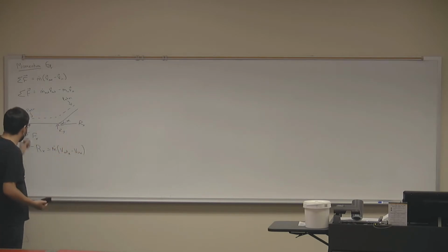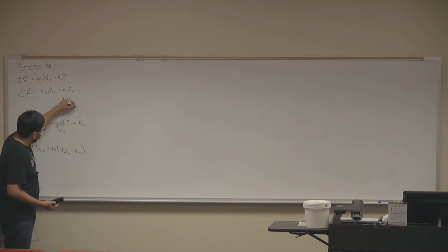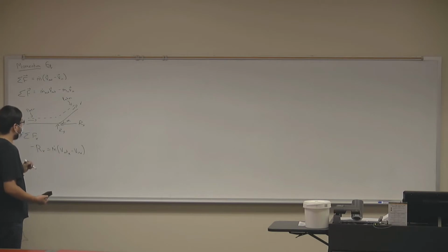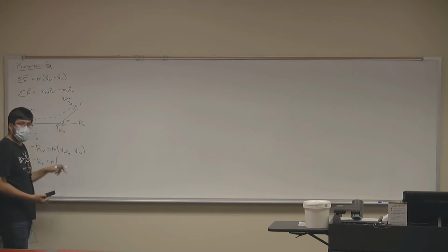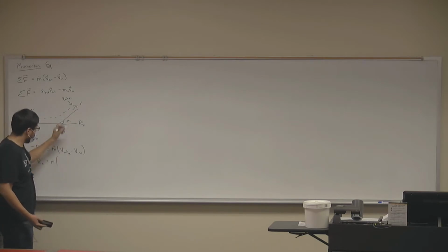And why does that matter? Because if your flow enters your deflector with one velocity, leaves your deflector with the same velocity, then we can find these components as a function of the magnitude of the velocity and the angle of deflection. So we said that in the x direction, you had that the outlet velocity, the velocity of the fluid leaving the system, was equal to velocity times cosine of alpha. Is that correct?